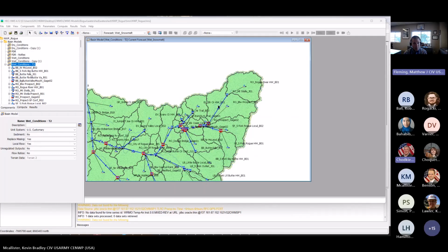A slightly different PX, if you use one PX for both subbasins versus a slightly different PX. You're not thinking the PX is 34 in the lower subbasin and 40 in the upper, right? It's not that drastically different. No. So if the difference between the two subbasins is slight, like 36 versus 35, and then if you combine them, you're using 35.5, it's a wash. You're not going to see that big of a difference at the outlet of the subbasin.